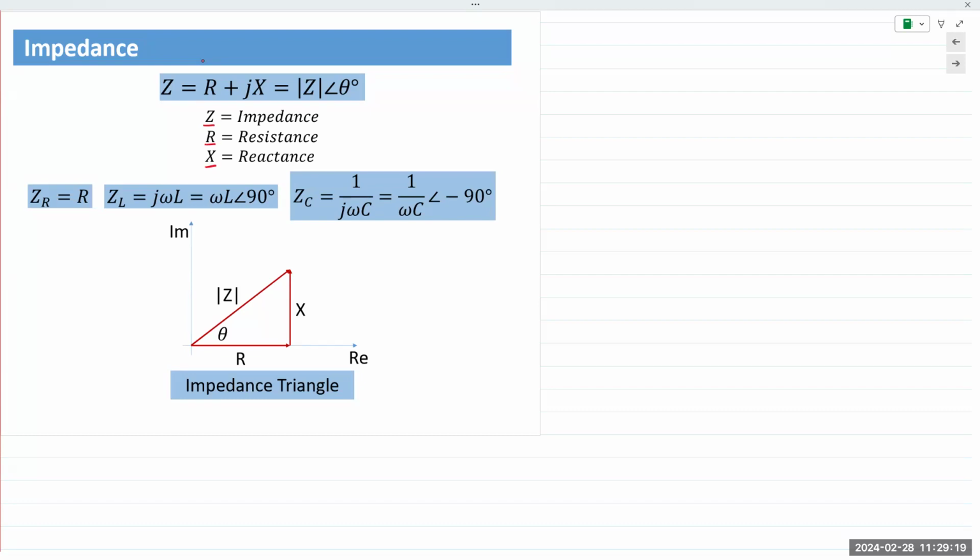The magnetic field and the energy stored in that magnetic field give rise to an opposing voltage that has opposite polarity to that inductor voltage. Now, when you try to change the current flowing through that inductor, that magnetic field is going to oppose any change in that value. Remember, if it's constant, the inductor behaves like a short circuit. If you try to change that current, it's going to oppose any change in that current. That opposition is reactance.